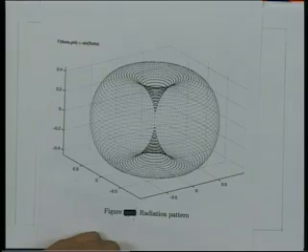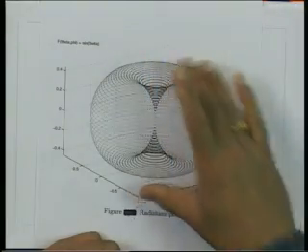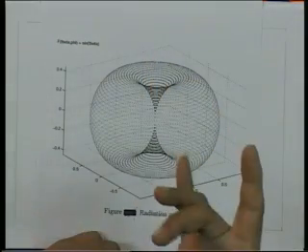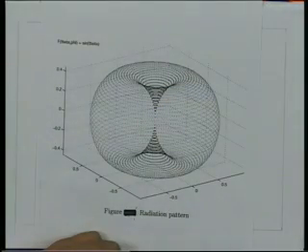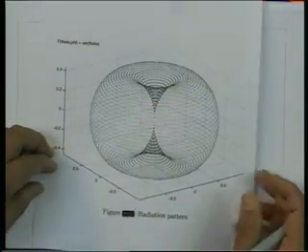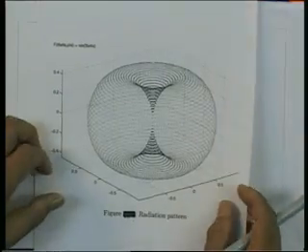So, we got now the sections of this general 3-dimensional surface by 2 principal planes, the E plane and the H plane. This 3-dimensional figure can now be described by two planar figures, which are sections of this 3-dimensional surface in two planes, and these patterns we call the E and H plane radiation patterns.